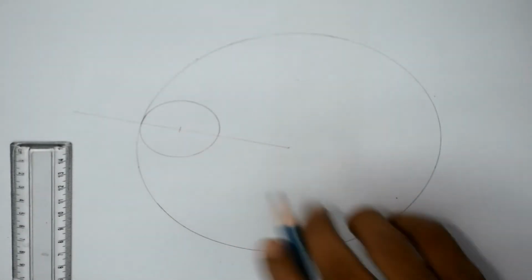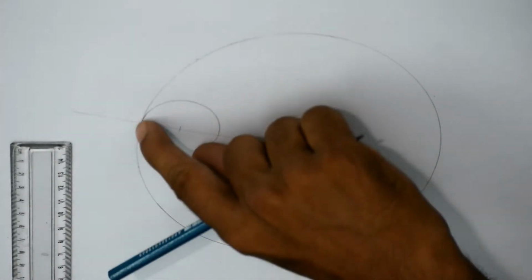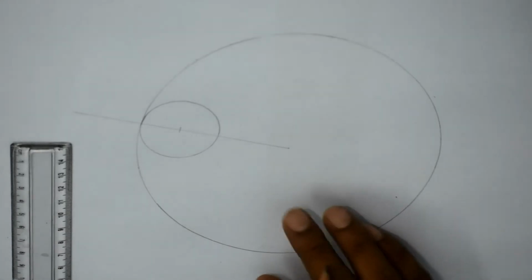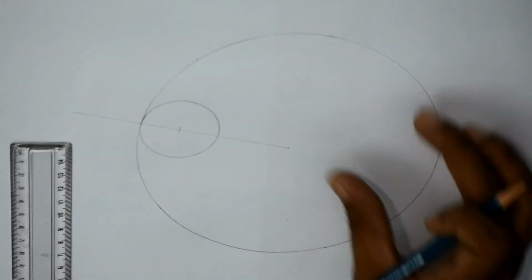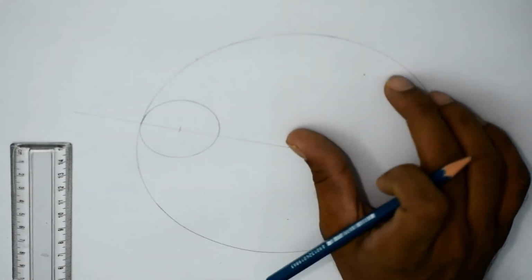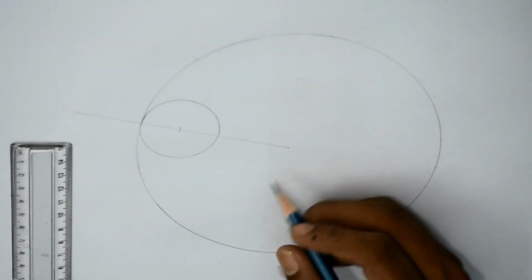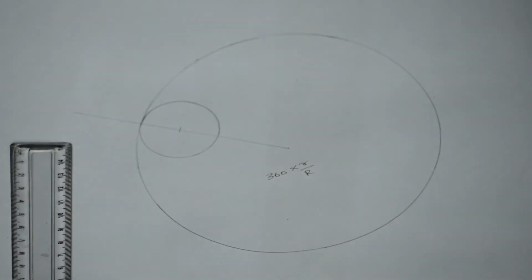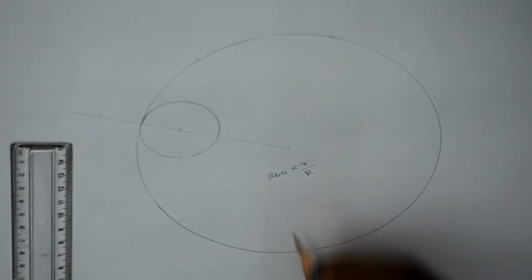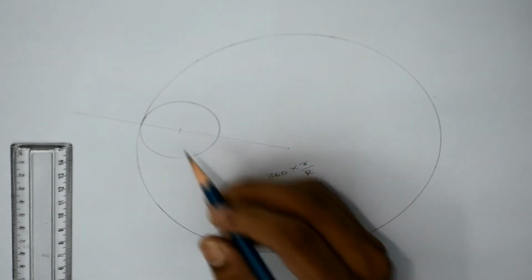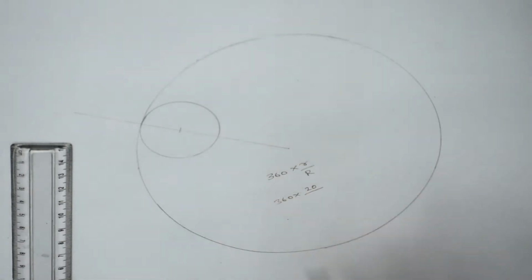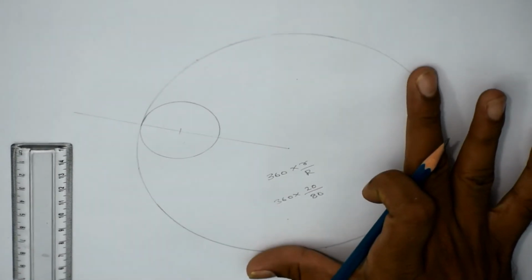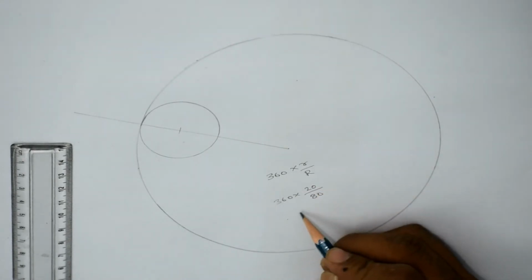So now we have the rolling circle. This circle, as I said earlier, will roll inside this directing circle. Now coming back to our hypocycloid, it will not cover the whole directing circle. It will take only some small portion, a particular angle which can be found by this formula: 360 into r by R, as we did last time for drawing the epicycloid. So here the small r is 20, the radius of the rolling circle. The capital R is the radius of the directing circle, which is 80 because the diameter was 160.